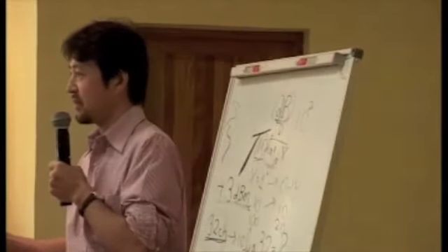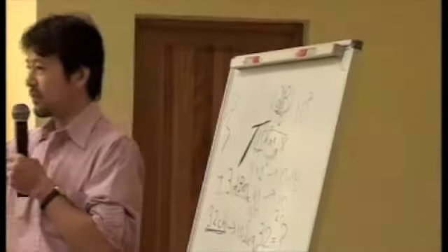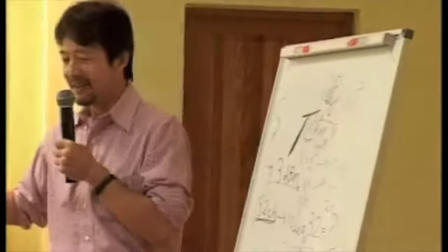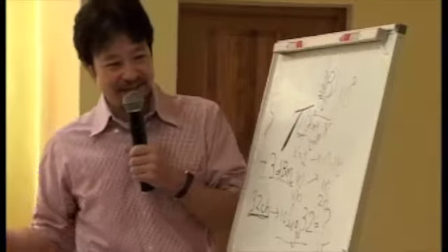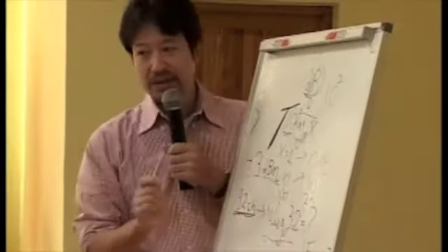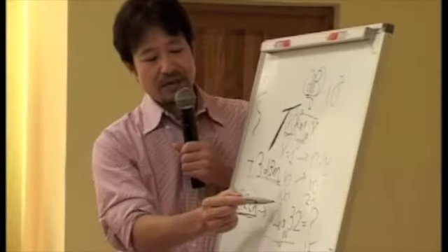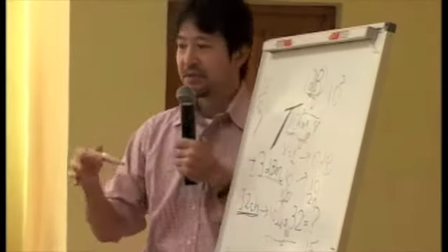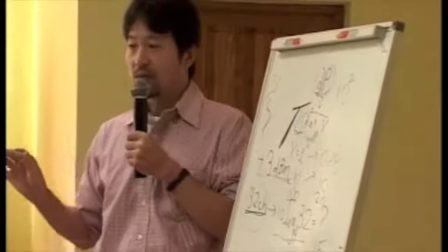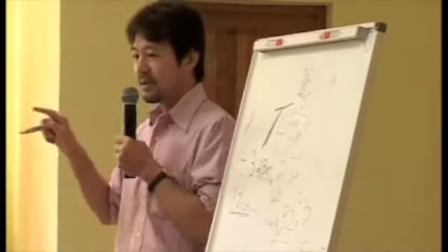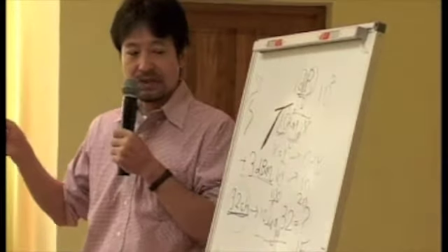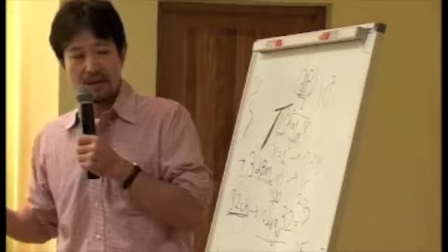If this bottle is 1 liter, 10 liters is a bit strange, but 10 dB larger than this. 20 dB means 100 times larger than the compared value. Of course, if 1,000 times larger, we say 30 dB.